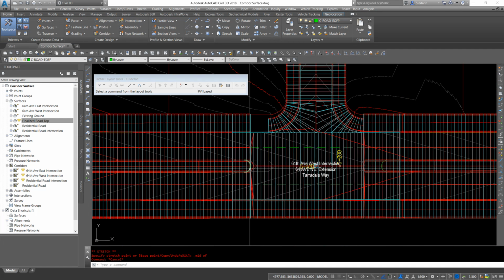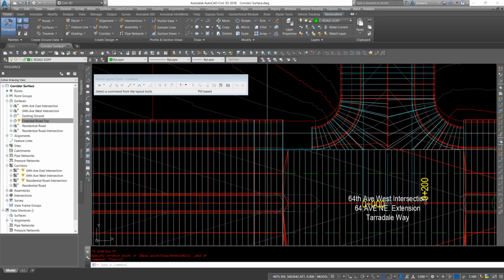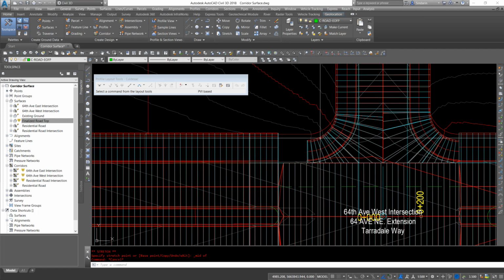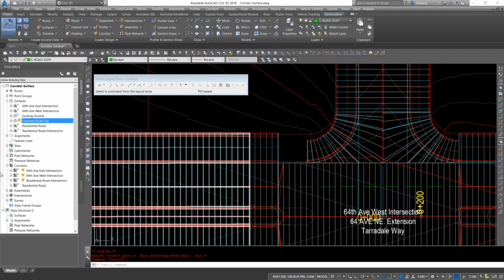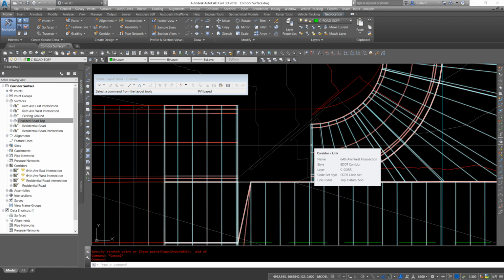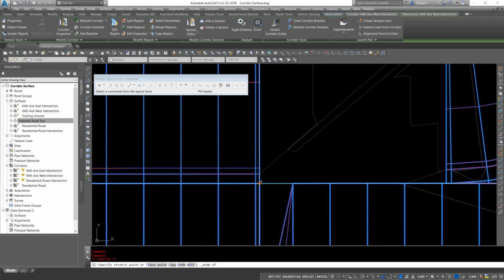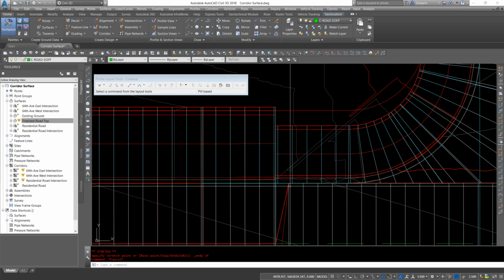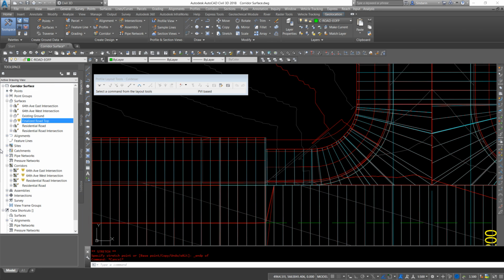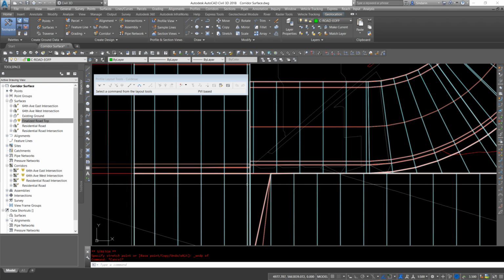So we have moved that section now a little bit, but it leaves us with some open space around our sidewalk here. Now, if I rebuild this surface, we can see how it causes a problem. So again, we'll select the corridor, and there's a grip here for the sidewalk region. I'm going to snap to the end of this line. So I'm just tying them back together. And yes, the curbs don't quite line up. That's because these two roads have slightly separate curbs.